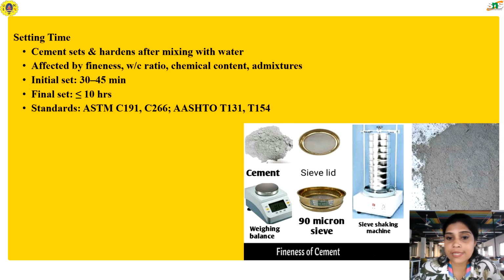To ensure quality, standardized tests are used, like the Vicat needle test, ASTM C191, which measures penetration resistance at different times, and the Gillmore needle test, ASTM C266. This is all about the setting time.